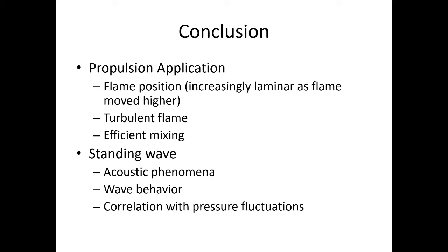As the acoustic waves drive better mixing, pulse combustors can be used in a case where mixing is very important. In addition, the standing wave observed inside the tube was also very significant, as it showed an acoustic phenomenon as well as how pressure fluctuations affected the acoustic vibrations and acoustic fluctuations inside the tube itself.